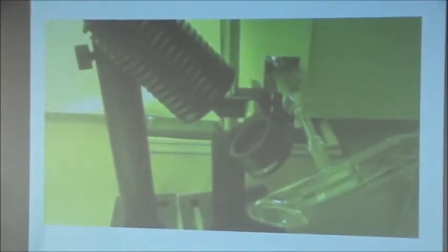So I was telling you how a laser pointer does this. Here, this is a handheld laser. This one actually costs a couple $100, only a few tens of milliwatts, from a company on the East Coast here. And what I have here is a small glass tube, a mini vacuum chamber, which we made so that we could move it around and demo it. And what you see is an aluminum electrode here. On it you have the nanotube forest. Then there is a counter electrode here, which is not connected to the forest. There's a gap between them. You can't see it very well here, but that's for collecting the electrons that come out.